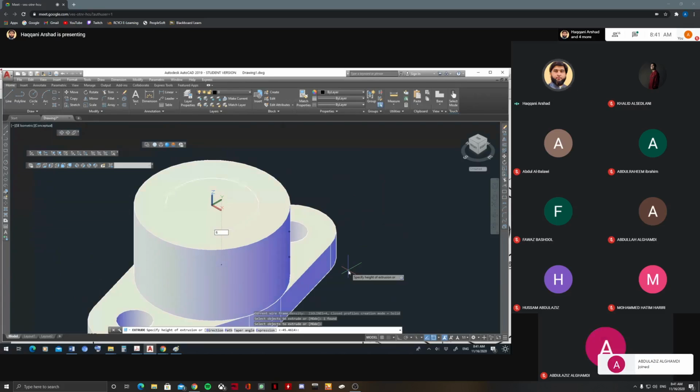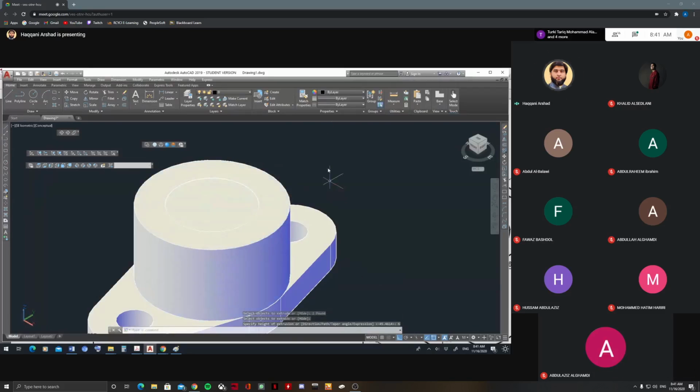The depth is 6, so it will be 6. Okay, maybe it is not visible, but you can easily delete that one. So go for subtract, click the main body, enter, then click this one, enter. See, you got the hole there, which is depth of 6.